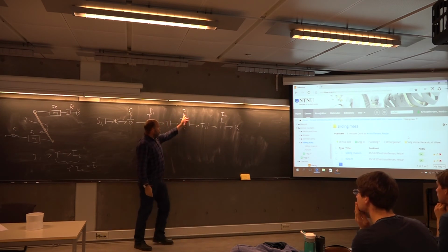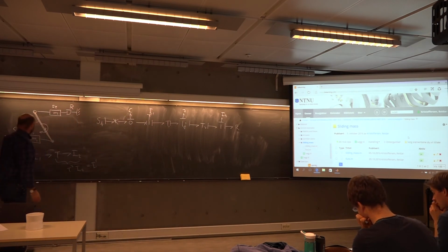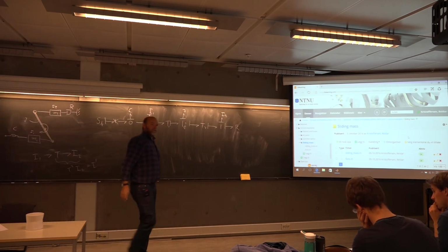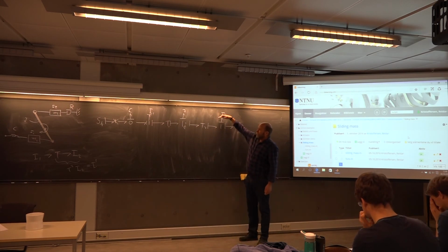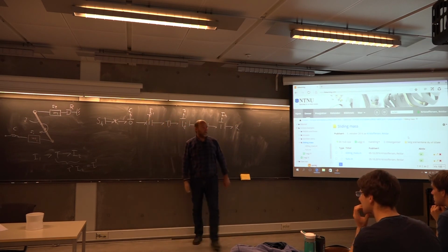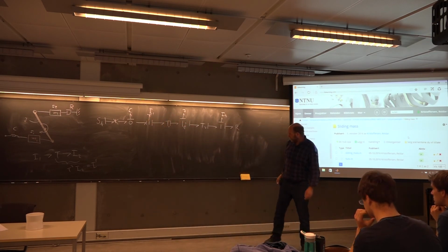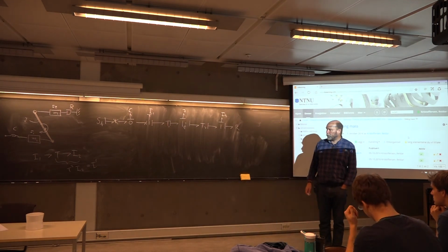So now I have 2 masses, both on the differential form. And again, since all 3 masses are directly coupled, if you know the motion of one of them, you know the motion of the 2 others as well. So it's still just a second order system. And you can play around with this if you like. You could have chosen the integral causal stroke here, for instance. Then the rest will be dictated to be differential and differential. Just try. So you see, it didn't change the dynamics in the problem at all.